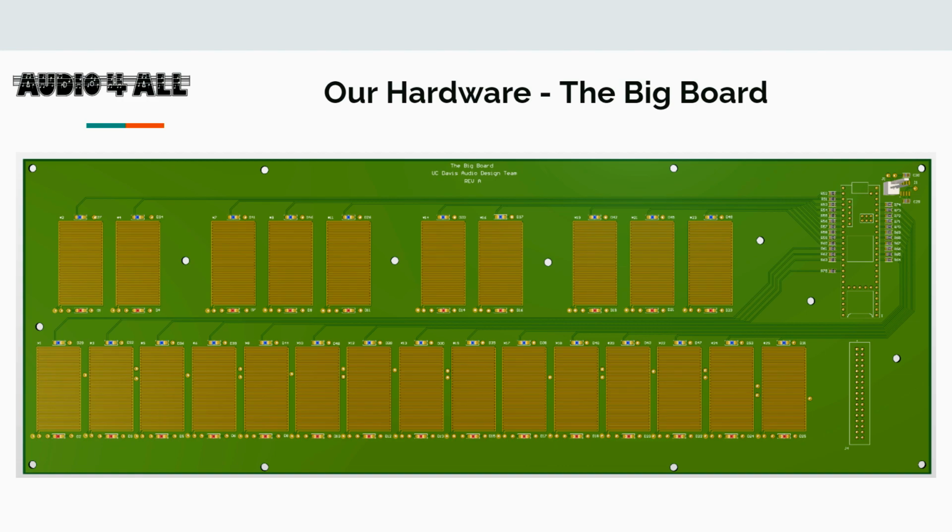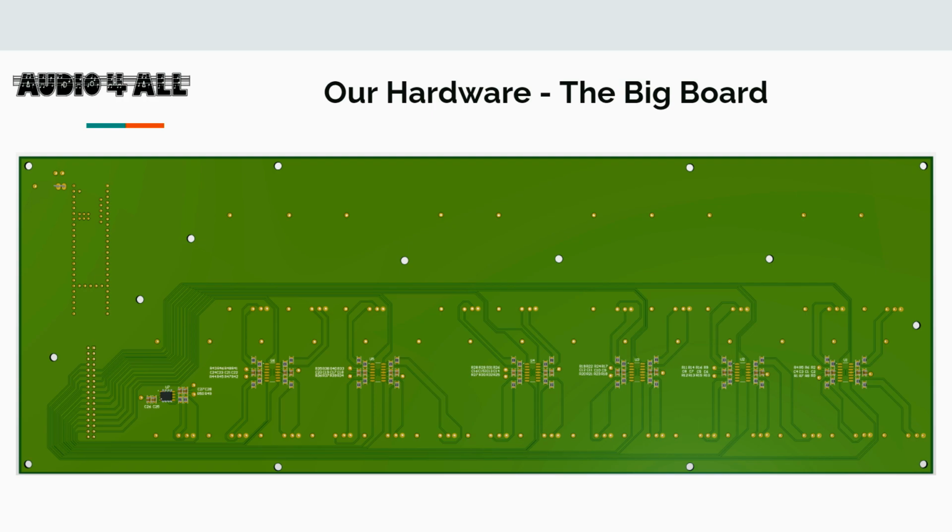The board contains 25 force-sensing resistors for note input. The footprints for each of these sensors were designed for natural playing sensitivity, since the space and trace of the sensors directly controls their force versus conductance curve. Each sensor routes to a header that directly connects to Bela through a ribbon cable, as well as a Teensy microcontroller that communicates with the Jetson for chord recommendations using the I2C protocol. The conditioning sensors for the FSRs were placed on the back of the board, and a 4-layer design was used.